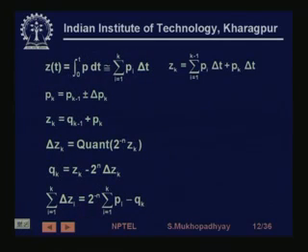Now, while doing that, the only thing is that we don't want to send multi-bit numbers in the case of a reference pulse system. We want to send single bits. So how do we do that? Our simple strategy is that we keep on adding a fixed increment, and whenever this sum exceeds a certain number, then we send a command to the motion control system that now make this motion.